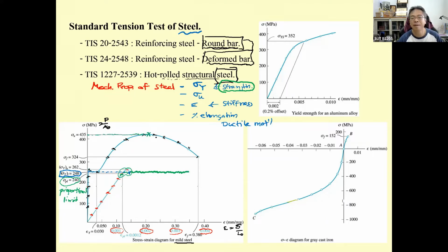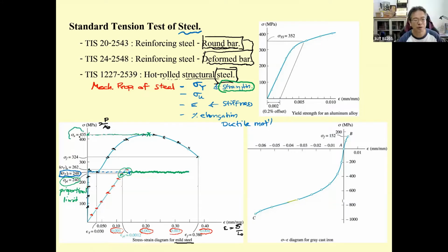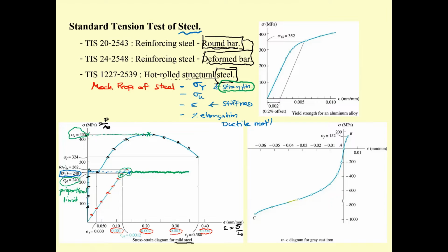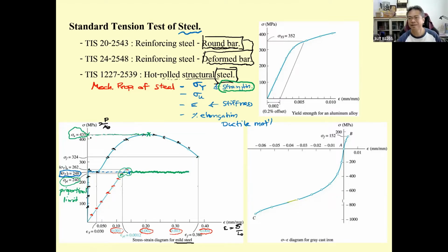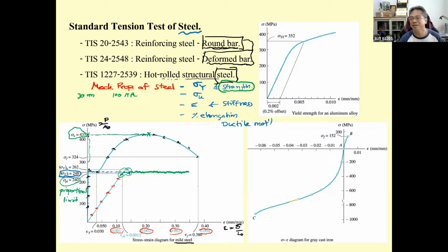And then if you need to find the second one, that is going to be the highest stress the material can take. This one can be computed by proportion, like the previous one I taught you, not by guessing. If this length is, say, 30 millimeters for 100 megapascal, and then you measure this one for 10 millimeters. One person may measure 9, or another may measure 11.